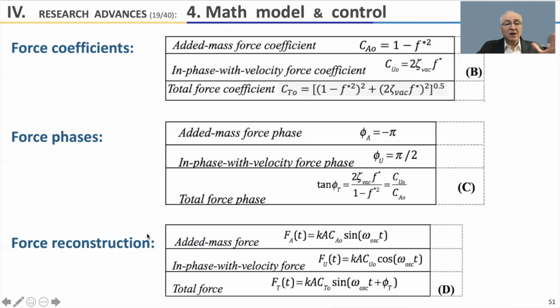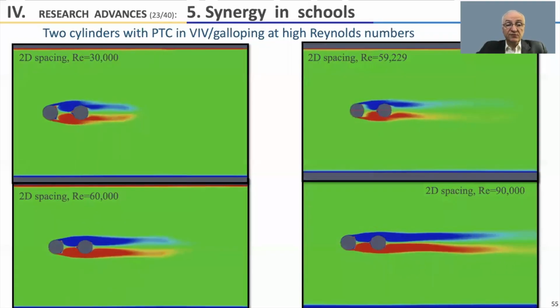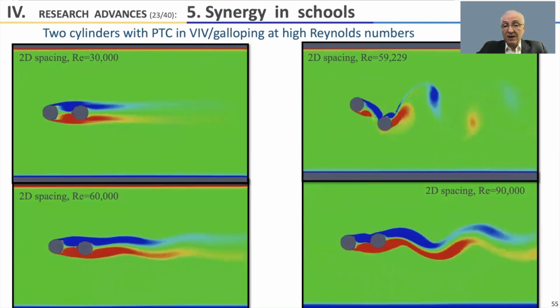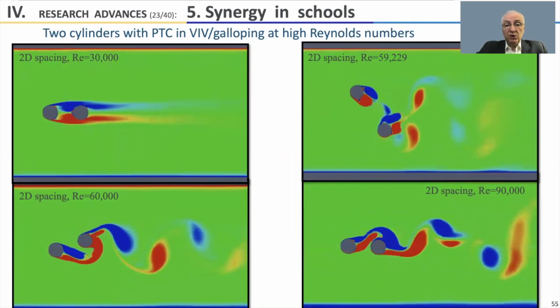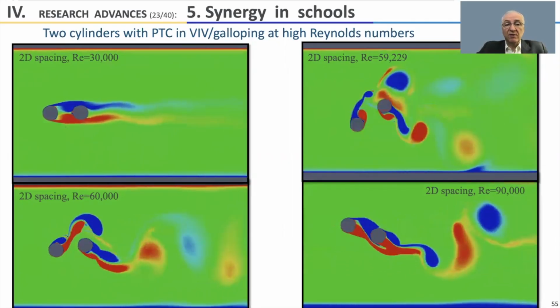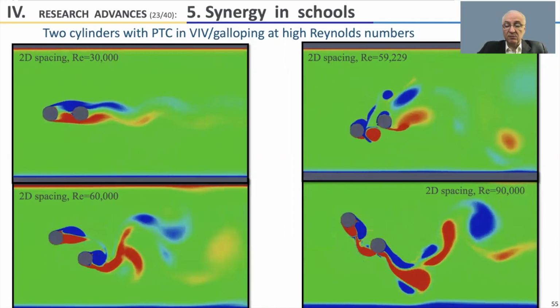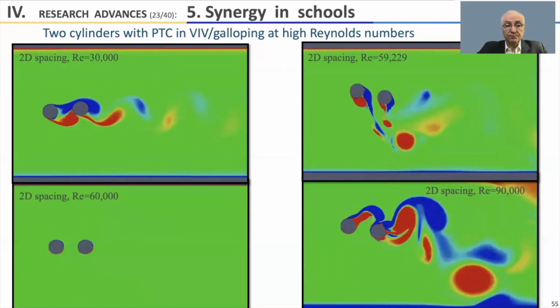The results are in very good agreement with experiments. We're working on second order terms right now, even though they are not so significant. Synergy between cylinders is very complex. Computational fluid dynamics helps us a lot. Again, as I mentioned, the important thing is the timing between vortices, bodies, and shear layers. We have identified 9 patterns. Again, some of those generate power and some do not.